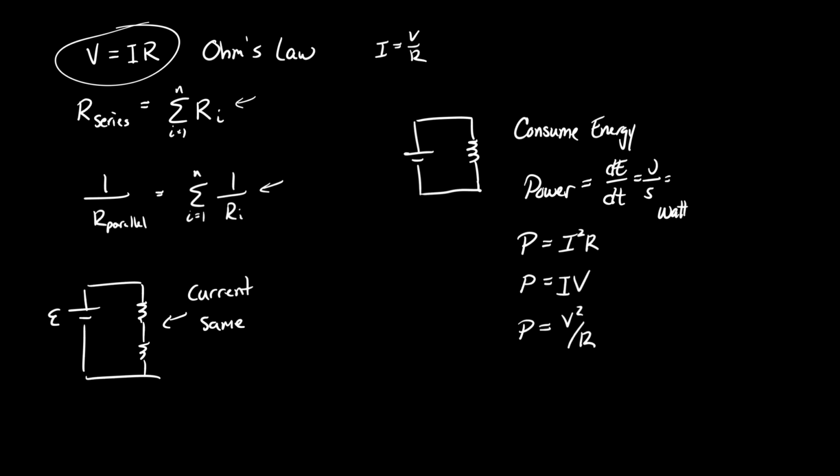That should make reasonable sense based on Kirchhoff's rules. So, if I have a parallel element in a circuit, what's a reasonable assumption about the resistors that are in parallel? Say again? The voltage, that's right. For resistors that are in parallel, the voltage should be the same.